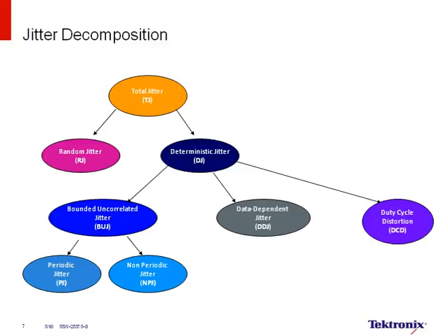The next question is, I'm using DPOJET of Tektronix on a DPO scope. Where can we change the clock recovery method as mentioned in your last slide? Okay, so I believe if you go to that menu, first of all, you've got to pick the measurement you are setting.